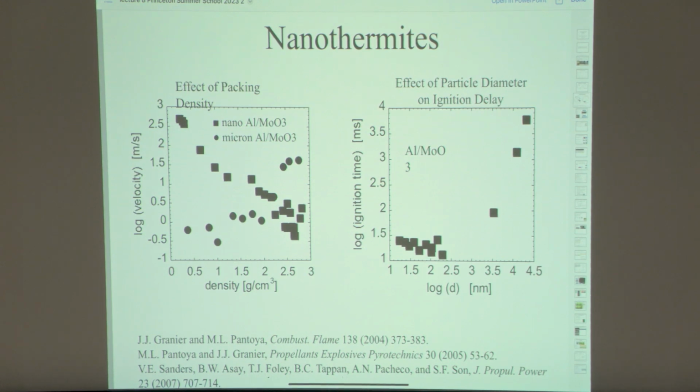In the nanopowders that are not packed to high density, I have voids between the spaces of the powders. And so what happens is the reaction rates are very fast locally, and you create a lot of gas locally. So it creates an overpressure, and I use that overpressure to create a convective wave upstream. Instead of conductively heating the particles, I'm convectively heating the particles. So it's a convection wave instead of a conduction wave, and you can get these very high speeds as a consequence of that. That's the same thing that's been seen in granular beds of propellants as well.